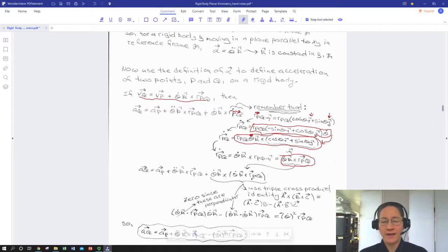So we're going to put that back in, this expression, and then bring all the other terms down and just rewrite them. So we've got first term is just acceleration of point P, the point for which we presumably know the acceleration. Then we've got what's effectively our angular acceleration directed in the planar normal direction, crossed into our radius vector from point P to point Q. Now, we've got our rotational velocity crossed into what's in parentheses.